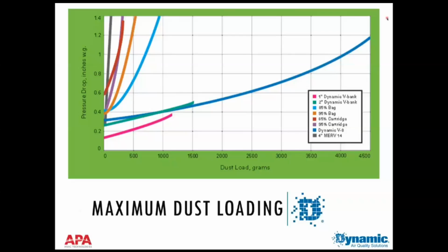So the media pads themselves are an inch deep and 9 layers of different materials, versus a typical high efficiency passive filter, which is a relatively thin, relatively flat media that's been pleated up, and so it doesn't have a lot of loading capacity. It has a lot of surface area, but not a lot of loading capacity. So we're able to load through that entire depth.